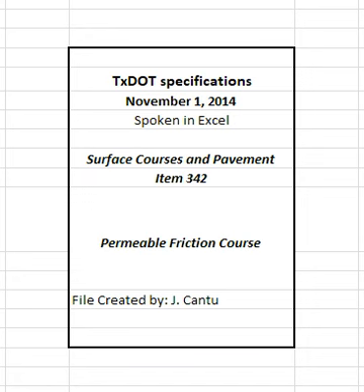4.3.2 Material Delivery and Storage. For material delivery and storage, include the sequence of material processing, delivery, and minimum quantities to assure continuous plant operations. Aggregate stockpiling procedures to avoid contamination and segregation. Frequency, type, and timing of aggregate stockpile testing to assure conformance of material requirements before mixture production, and procedure for monitoring the quality and variability of asphalt binder.